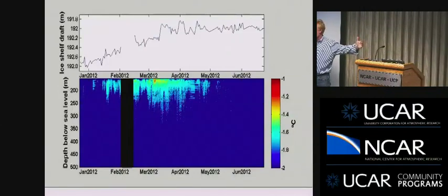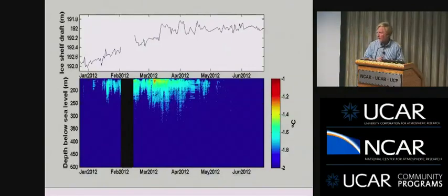And so it can resolve typically temperature fluctuations over 2 meters, Nyquist kind of stuff. We were able to resolve melt rates at a millimeter per day from those individual 1 meter measurements. So you can get a lot out of this kind of instrumentation if you think about it. And again, it all comes down to not the absolute temperature, but the gradient. And if we can resolve the gradient, we can learn a tremendous amount about what's going on.